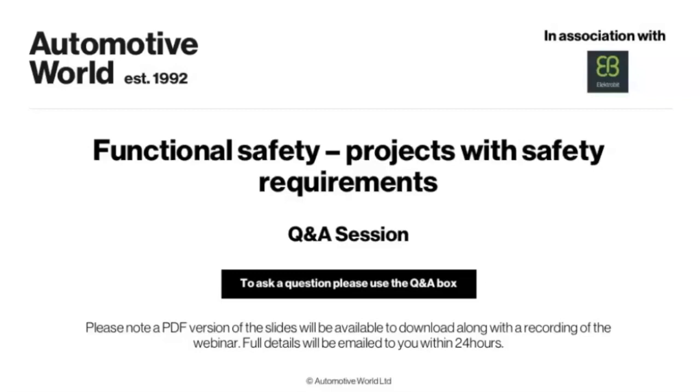If I have functionality on an ECU which has safety requirements and influences a system feature which is safety relevant, it could still also implement features which do not have a safety implication.